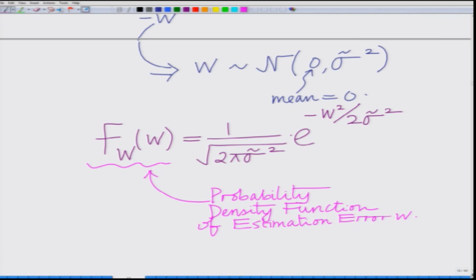So what we have done in this module so far is we have started to develop a framework to characterize the reliability of the MMSE estimate for this scenario of Gaussian parameter estimation, where the parameter h and the observation vector y bar are jointly Gaussian. We said that the posterior probability density of h is characterized by the mean h hat and the variance which is given by the MSE.